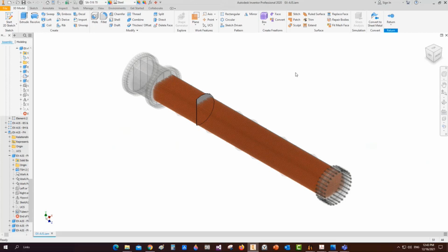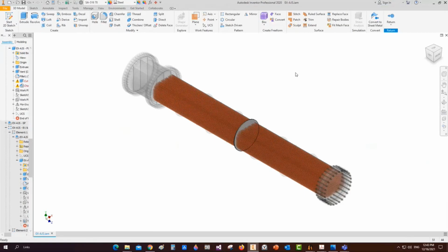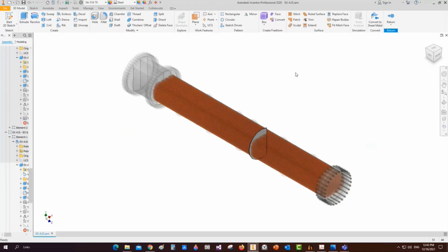So can you imagine how much time you will save in case of using the SEG tools to make the elements and this stuff of work, like make a holing pattern for tubes and tube sheet and baffles? All of that SEG can take care of. If you would like in a special case to make some special things, like we will discuss how to make, for example, the eye bolt holing to pull out the tube sheet outside the heat exchanger, something like that, we can do it easily, and I will show you how to make it manually, how to add some additional things that you would like to make if it's not included in SEG.